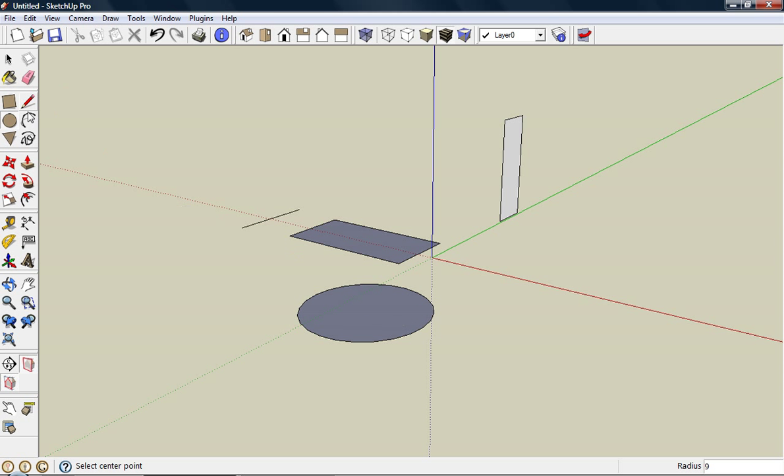If you look at that label on the measurement toolbar, as I select the arc tool, you'll notice that the radius label is gone, and I've lost the input for a new radius. That's because I moved on to the arc tool. With the arc tool here, we've got two inputs to make. The first is the length, which will be the chord of the arc, or the distance that the arc will span. We can enter that manually in the measurement toolbar too if we want.